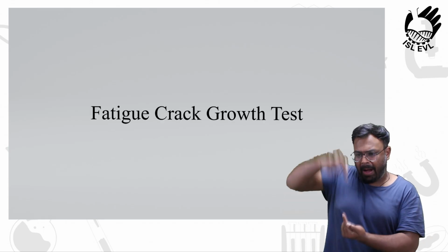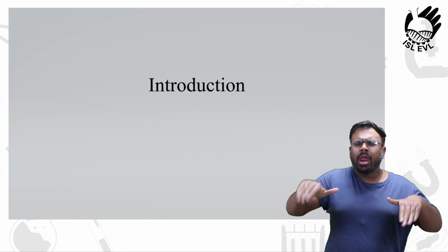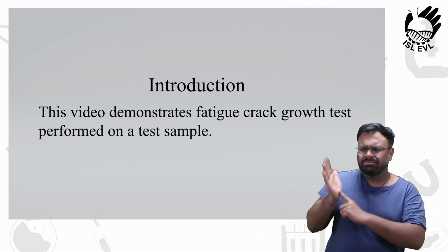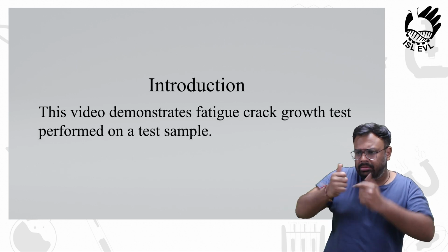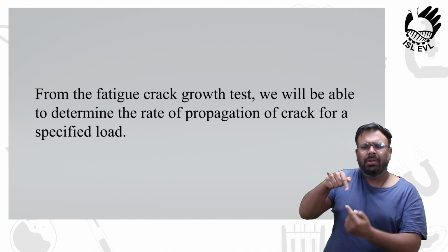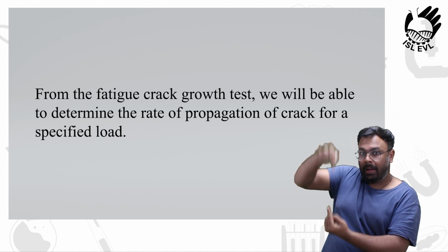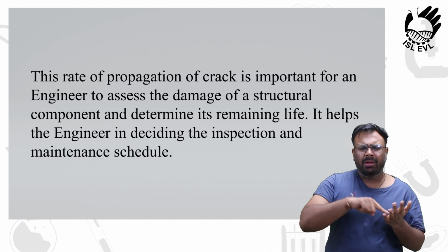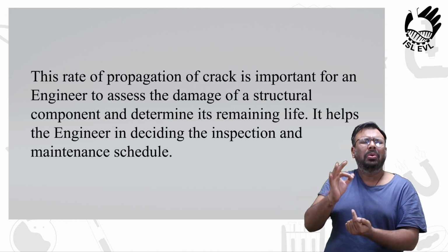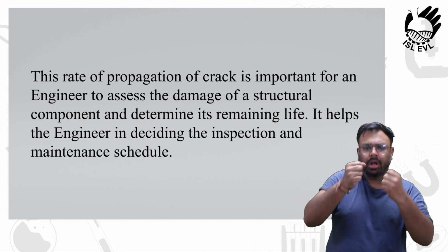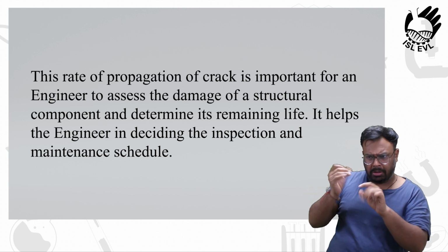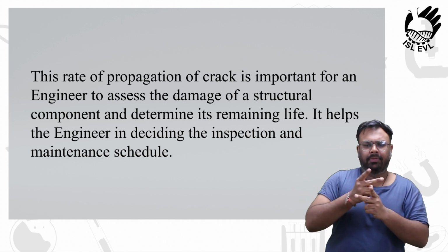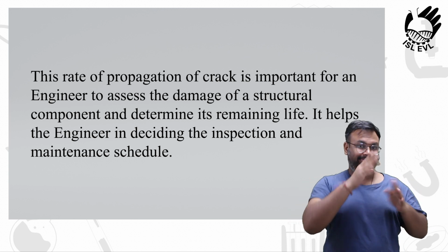Fatigue Crack Growth Test. Introduction. This video demonstrates fatigue crack growth test performed on a test sample. From the fatigue crack growth test, we will be able to determine the rate of propagation of crack for a specified load. This rate of propagation of crack is important for an engineer to assess the damage of a structural component and determine its remaining life. It helps the engineer in deciding the inspection and maintenance schedule.